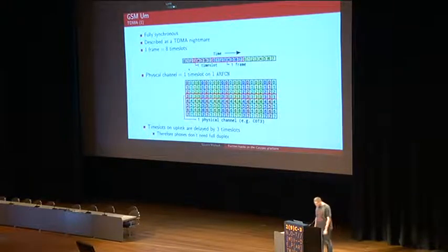So those bursts are not just transmitted at random times. GSM is a fully synchronous system that has been described by several people as a TDMA nightmare, because you essentially have TDMA inside TDMA. If you take the continuous stream of data on the RF frequency, you will find 8 time slots that compose a frame.